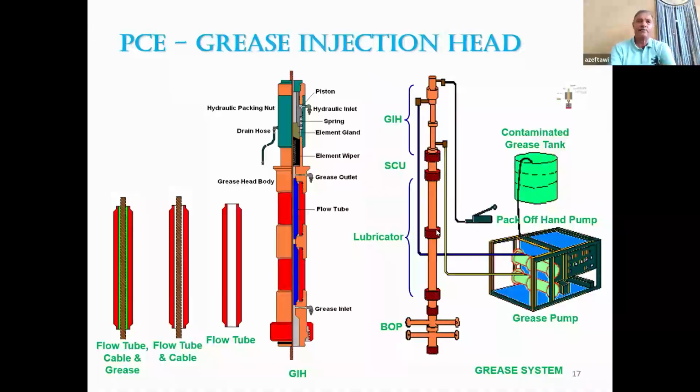Have you heard, guys, of a brass hammer? Why do we use a brass hammer in some applications? Normally the hammer has a wood handle, and at the end there is a block of steel. Sometimes, instead of a block of steel, we put a block of brass, and we use a brass hammer to hammer, not steel. Why do we use a brass hammer? To avoid spark.